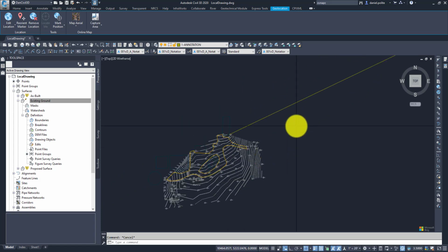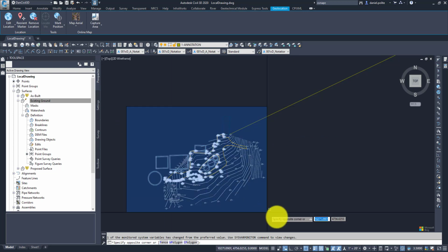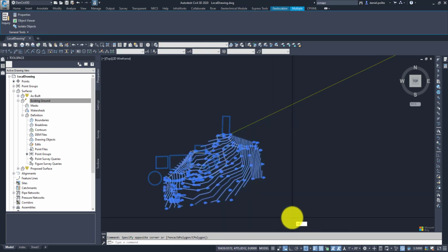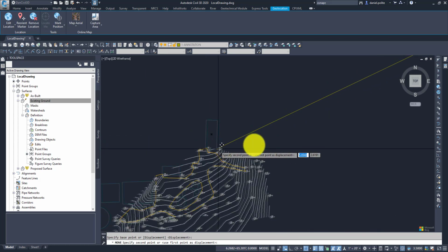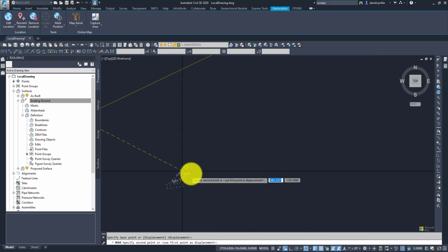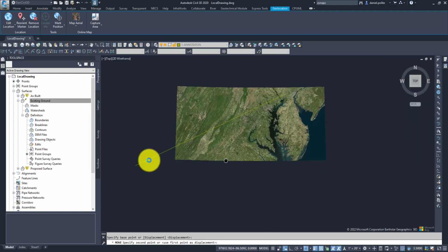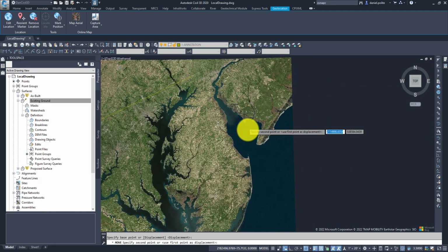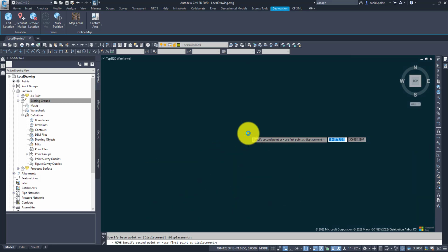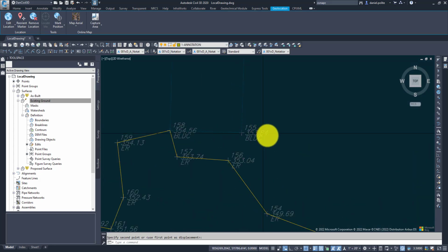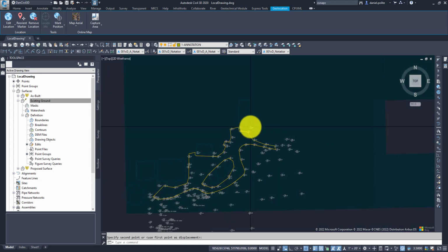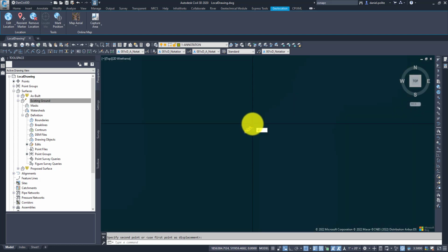So now if we set this O-snap Z to 1, we can select all our points and we select move. I don't have to go along any polyline, I can move them wherever I want. So just say I wanted to move them here. You'll notice that it doesn't change the elevation.